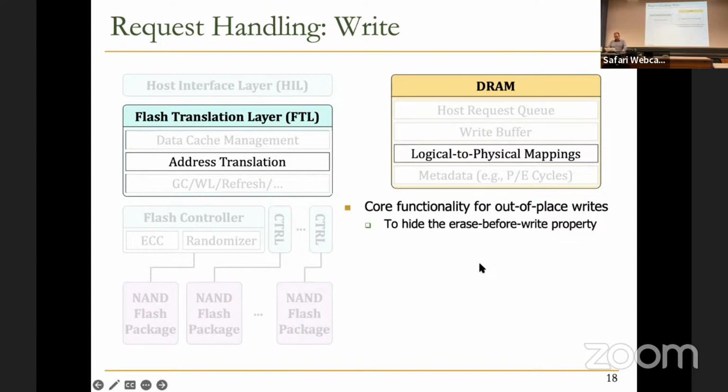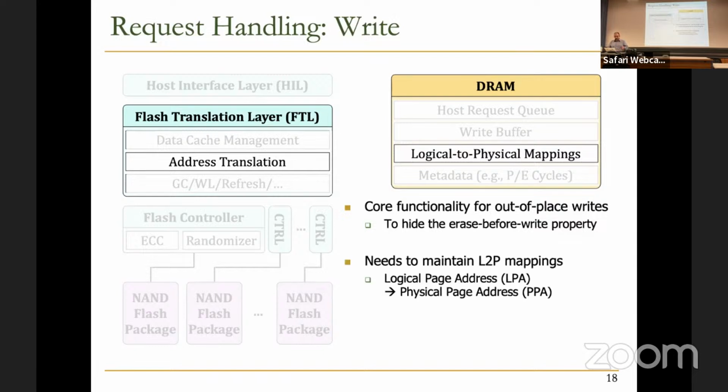We're going to learn about the reason. And that's why you always need to keep the mapping table. There should be a table that tells you which physical location each logical address from the OS is mapped to. That's one of the main uses of this DRAM. Most of the DRAM space is allocated to this logical-to-physical mapping.